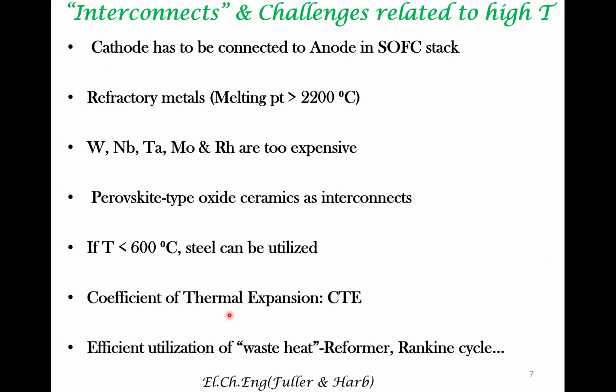In addition, because the products of SOFC, let's say even H2O, are at very high temperature, this waste heat should not just be released into the atmosphere. This is not very productive. So there are a lot of approaches on how to utilize this waste heat to do some other important function. One of the ways you can utilize the waste heat is to supply this heat to a reformer.